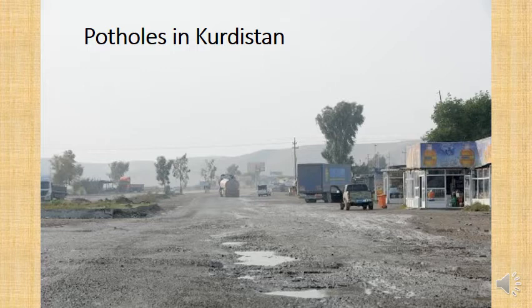And then when it rains, water can get in underneath the road. Another thing is it gets very hot in the summer, which means the bitumen loses its viscosity and it turns into a big puddle of oil on top of the road, which washes away. And then you're left with aggregate, which has less bitumen, and so water can penetrate into the road there.